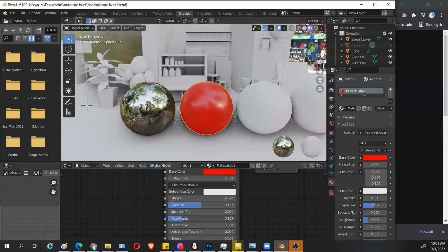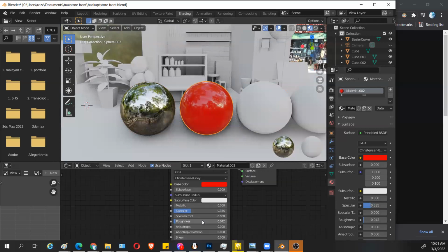Now this one, when you turn down the roughness, can also show the environment, although it's not metal, it actually is plastic. So for the metalness of the object, 1 gives metallic property to an object, 0 gives it a plasticky property. Okay. So specularity would be the shininess. All right. So that's what you could adjust.